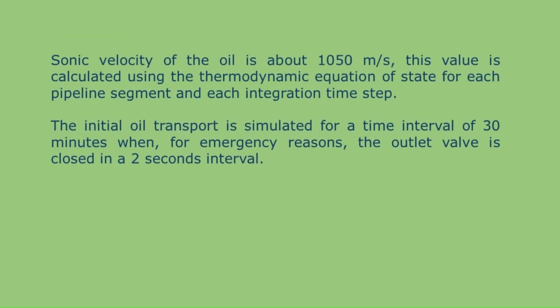The sonic velocity of the oil is about 1050 meters per second. This value is calculated using the thermodynamic equation of state for each pipeline segment and each integration time step. The initial oil transport is simulated for a time interval of 30 minutes when, for emergency reasons, the outlet valve is closed in a 2 seconds interval.